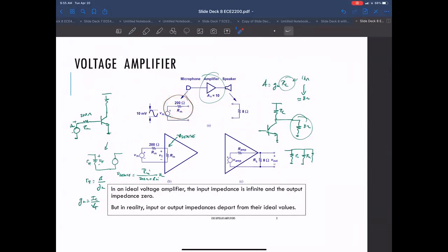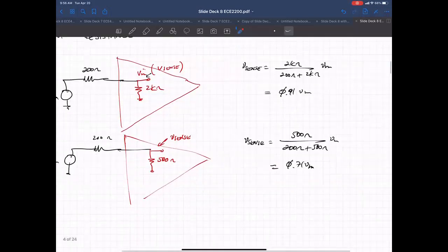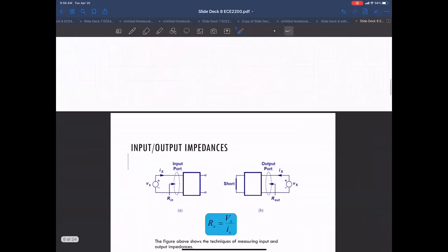So people also talk about source and load impedance. But in this class, impedance and resistance are the same because we're ignoring capacitive and inductive parts of the circuit, because we're having an early, more simplified introduction to these things. So if you hear me say input impedance, output impedance, source impedance, or load impedance, just interpret that as being resistance in whatever case, with impedance being the more general term.